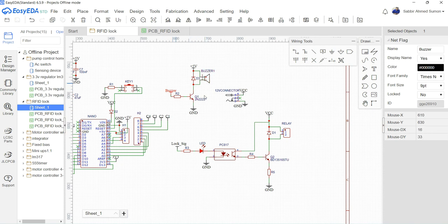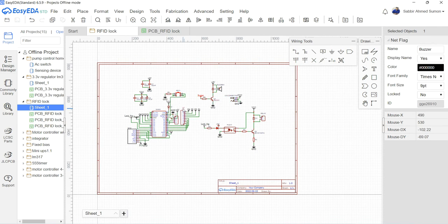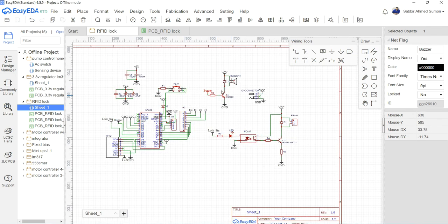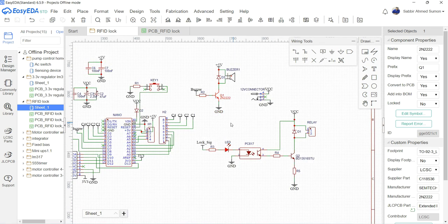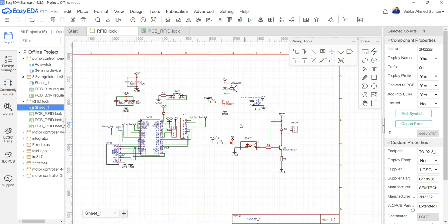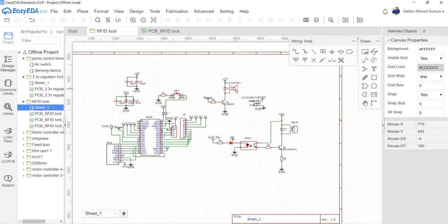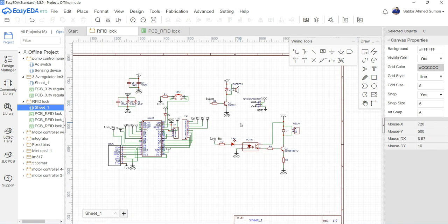And sometimes you may find many circuits on the internet where these transistors are not used. What happens then is that the buzzer is not operated at its full capability. The buzzer can draw 35 milliamps of current, but the resistor is chosen at such a value that it limits the current to 20 milliamps or less, so it beeps less loudly, which is not likable for me. So I connected a BJT to drive the buzzer, and that's all about this schematic.